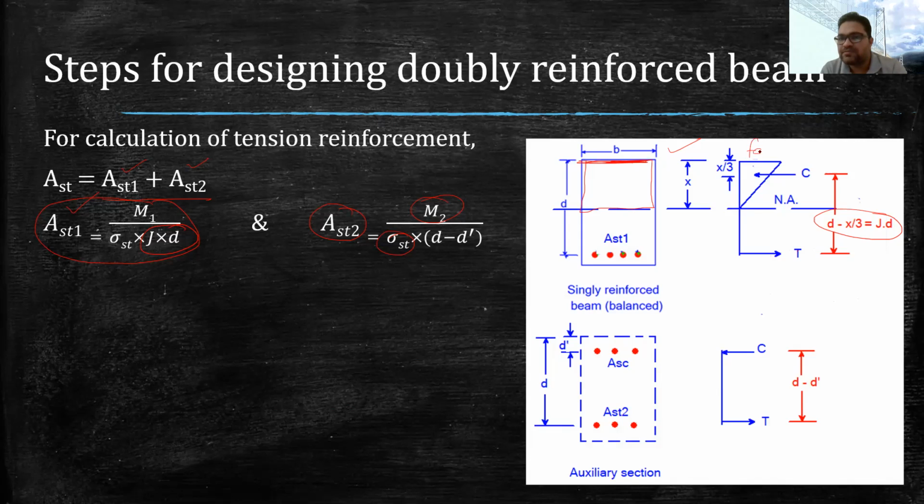So this is the FCBC. At the neutral axis, the minimum stress will be there. The stress will be varying linearly, and this is how we find out the triangular part of the stress. I mean, this is the variation of the stress across the depth of the beam up to the neutral axis, and the compressive force will be at the CG of this triangular area.